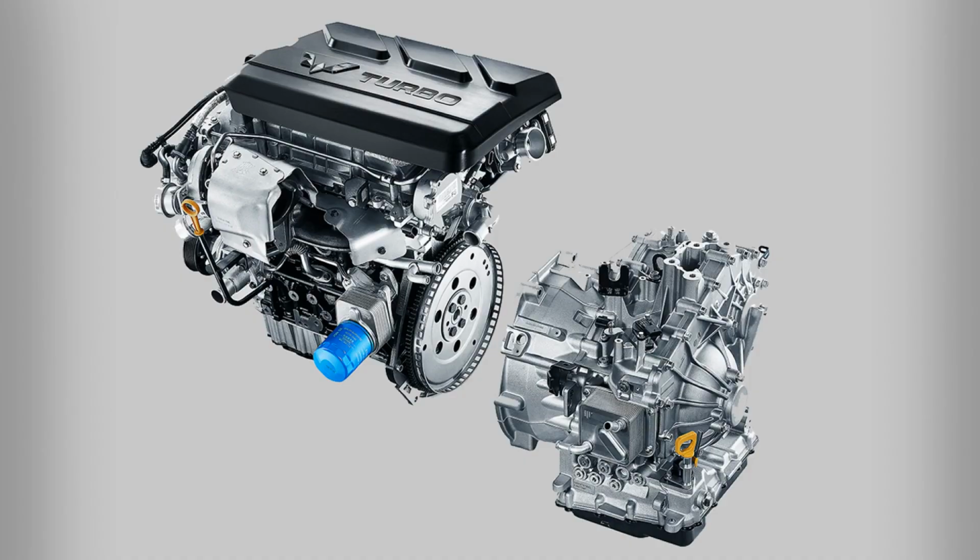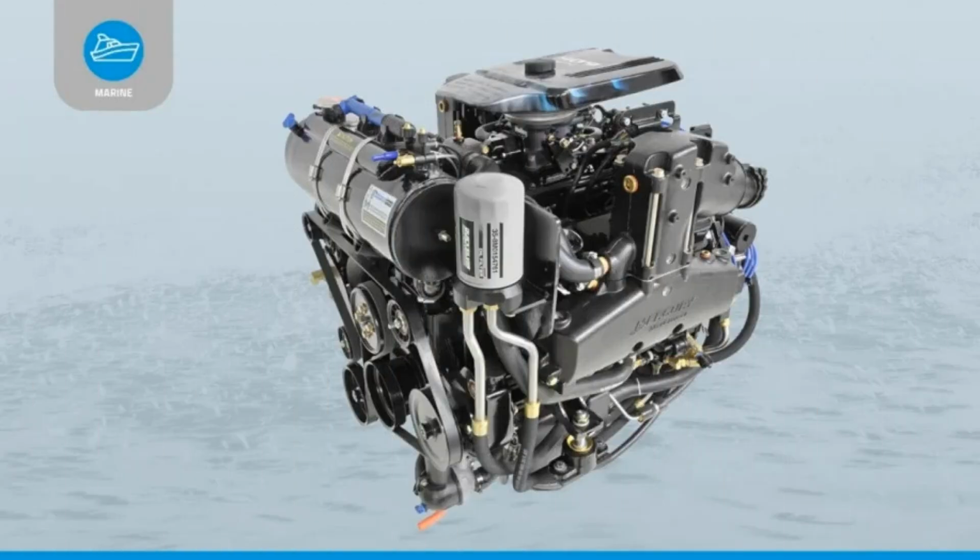For the most complete combustion of the fuel-air mixture, it is necessary to mix 1 kg of gasoline with 14.7 kg of air. Increasing or decreasing the share of air, we get an economic, lean, or power-enriched composition of the fuel mixture.